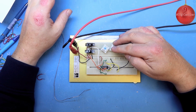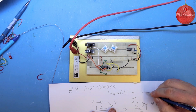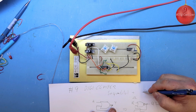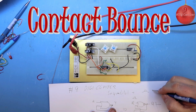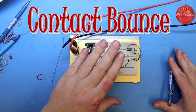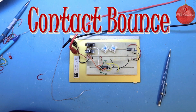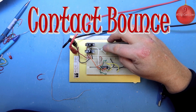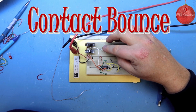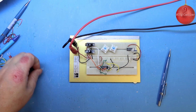But these switches are not immune to making prell, and that is when a contact, when you are hitting a switch like so, it will always bounce somewhat. It will not make contact at once. So there will be some glitches in this when you have some spikes and stuff when you are attaching a switch like this. But we are going to try without any capacitors or other tricks to make these switches good. Actually, the flip-flop is also a trick to make the switches more immune to what's in Norwegian called prell. I'm not sure if that's the right term for it, but it's when the switch is bouncing on the contact material, making noise when it's shifting from not closed to closed position.